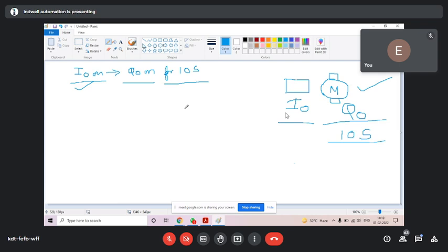Next, when we have a stop signal, from the stop signal, directly break the latch. Once more, please be attentive and listen to the steps. Then I shall implement on this example. Once more, to switch on NO, to switch off NC. Second thing, when we have a start signal, latch that with some flag. Next, when we have a stop signal, we break the latch from that. Okay, now I shall make this.